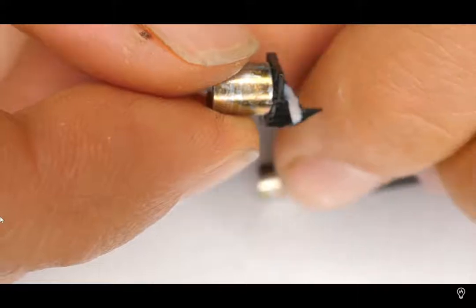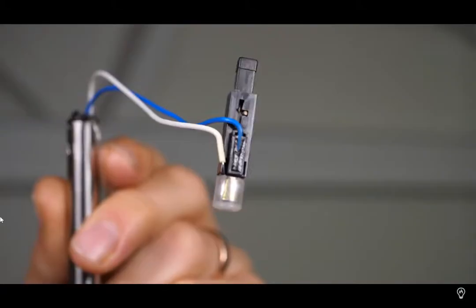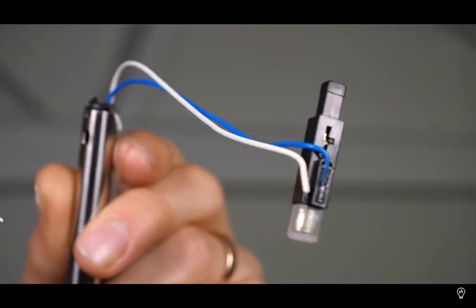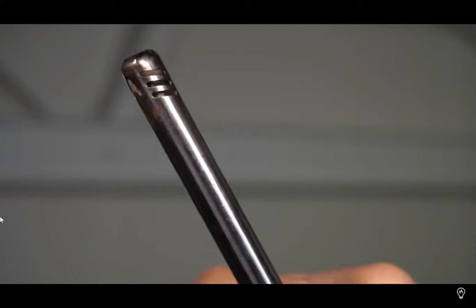The hammer then strikes a special kind of crystal called a piezoelectric crystal. And when you hit one of these things, it generates a voltage across the crystal. This is the inside of a barbecue lighter. This is the mechanism that houses the spring and the hammer and the crystal. These two wires are coming off the crystal and they're drawing that voltage up to the top of the lighter here.